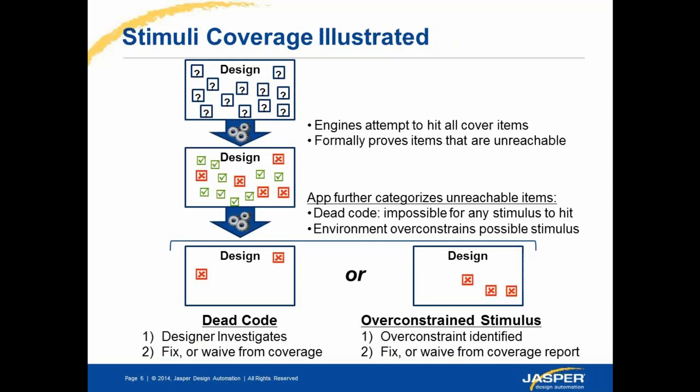In the first case, your designer runs your RTL in a completely unconstrained way. And whatever portions of your RTL haven't been hit are dead code. So the designer or the verification engineer can analyze the RTL and figure out if these portions are intended, or maybe it's just a default case statement you have put in there because your linting tool is complaining, or your company's design coding standards require a few statements.